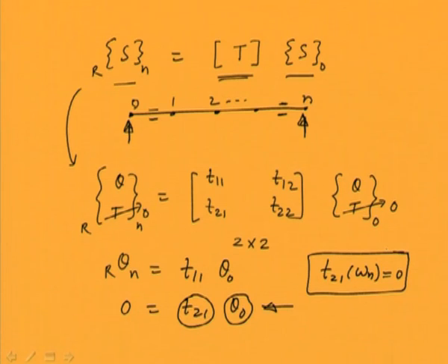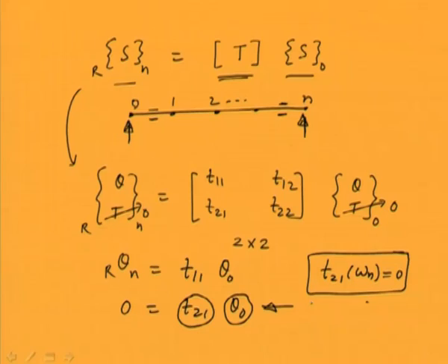So this particular equation, which will be a polynomial in omega n, is the frequency equation. This can be solved; if the polynomial is more than 4th degree, then obviously we have to solve using some numerical technique. If up to 3rd, we can solve using closed form solutions.